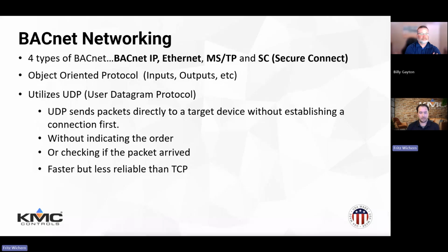What else? BACnet IP allows for communication across multiple subnets. I think we mentioned that. So you see that quite often for multi-campus control systems, and it can utilize the benefits of fiber and Gigabit Ethernet, as well as assigning IP addresses to devices. So we see that more and more prevalently coming up in